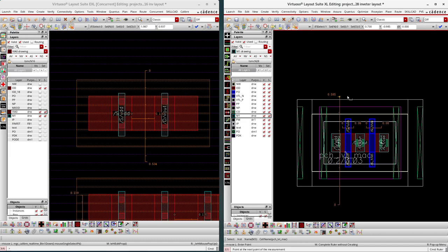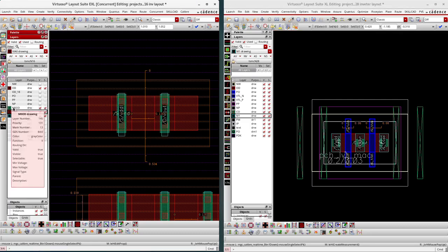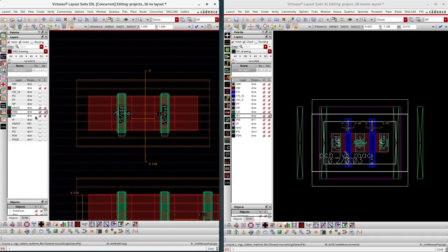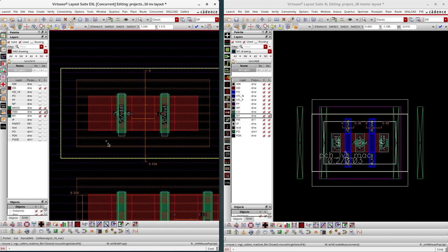But when you come to the normal planar MOSFET, whatever vias are there, we generally call that a contact. So there is no via 0 available in planar MOSFET. But in the FinFET device we have a via 0, and as well as that we have an M0 to OD layer. This M0 to OD layer is available in the same place where the source and drain terminal is. Because I am not very sure how this M0 to OD layer will be fabricated in the 3-dimensional view of FinFET. I think this is a kind of passivation layer or not, but I am not very sure about that. But these layers are present here.